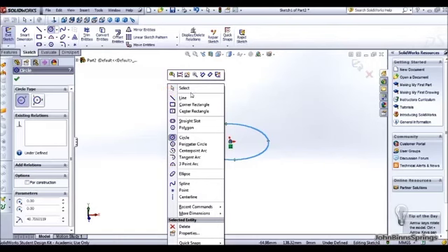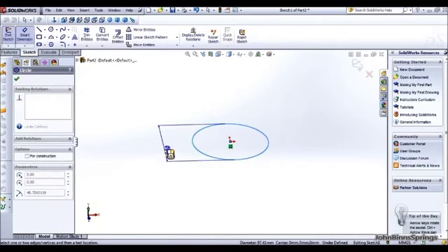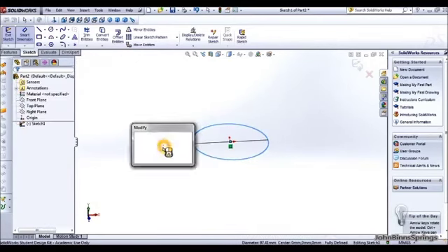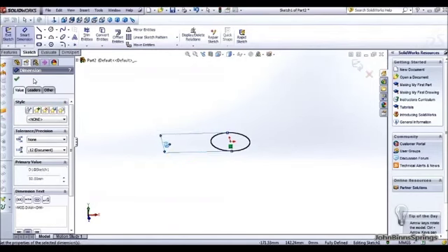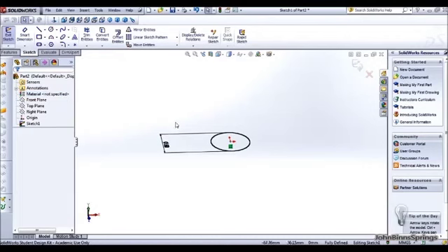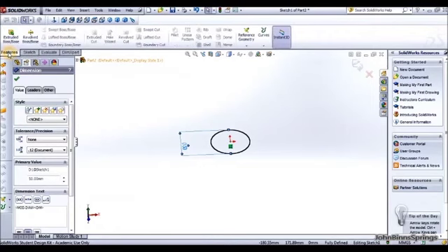You want to right click then as a shortcut and smart dimension that circle. For this example of a compression spring, I'm going to do it with a mean diameter of 50. You now want to tick that and move on to the next step, which is up here, click Features, over to Curves, and then click on the Helix Tool.